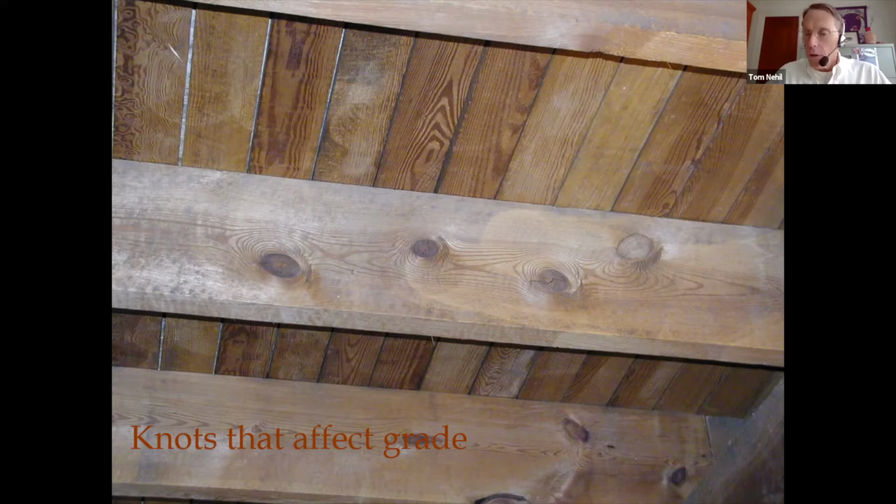We don't need to look at every single knot. We just look for the biggest one in the worst place. And that's the nature of grading. We think of timber and lumber as if it were a chain. And so we're trying to find the weakest link. And the weakest link occurs at the worst knot. So all we need to do is find that one worst case in a whole stick. And that kind of speeds things up for us, of course.